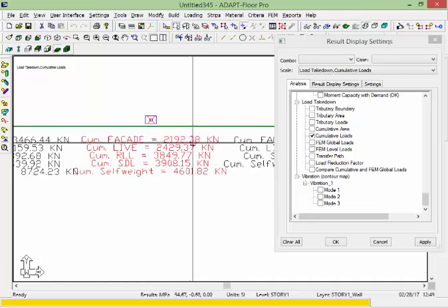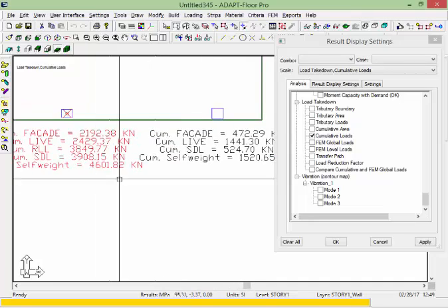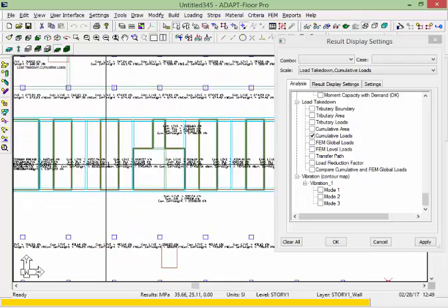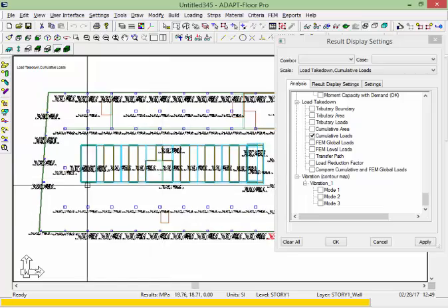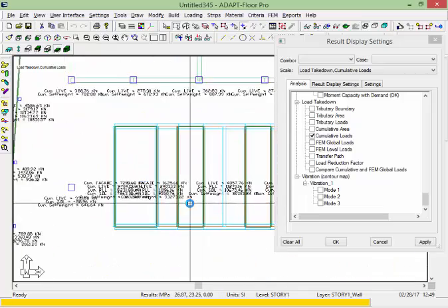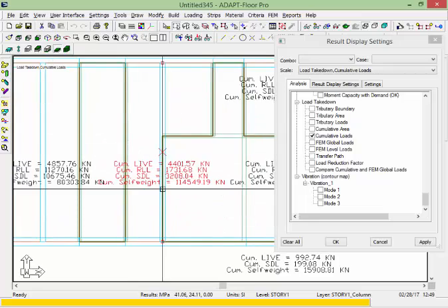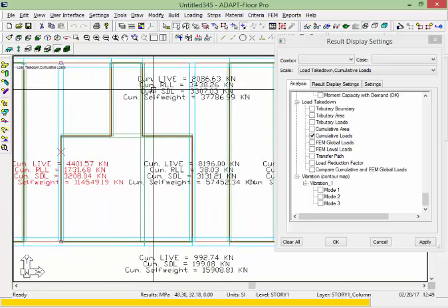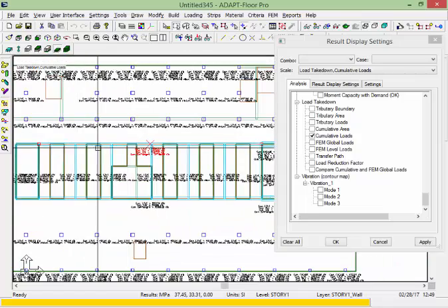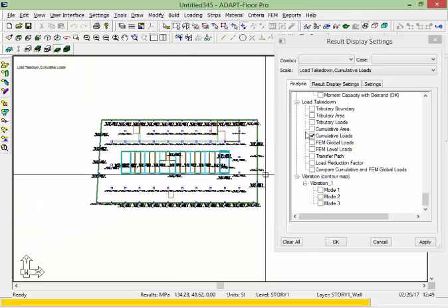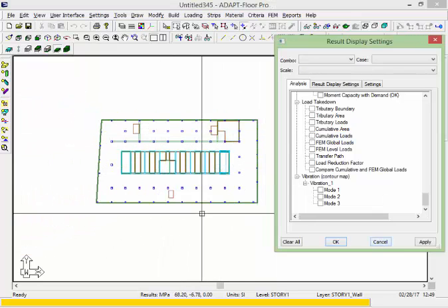And this is in metric, these are in kilonewtons. Each one of those supports at the base of the building, including the walls, has an assignment of reaction. Let's just, for example, take this wall. The reactions are shown here. We have reactions for this perimeter wall here, which would be applied at the centroid of that wall on the foundation. So we have the tributary reactions in place.